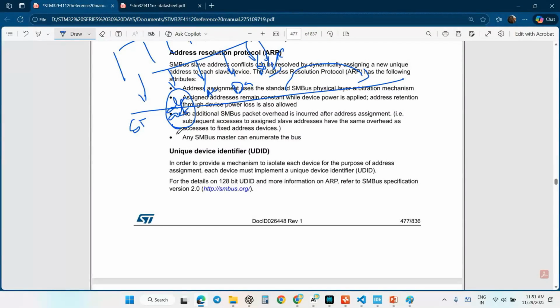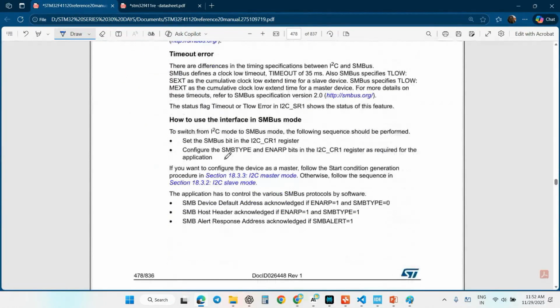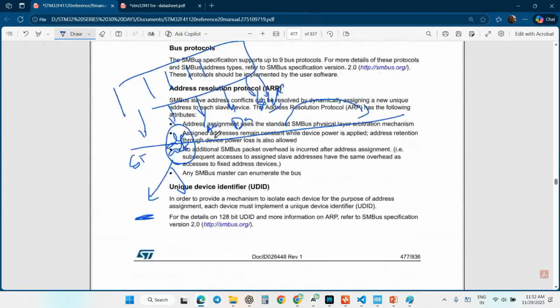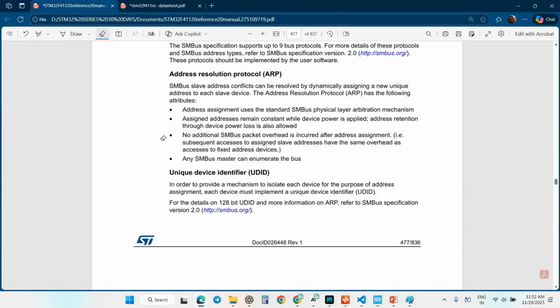If you are setting a data bit, there are multiple procedures. The size has to be mentioned: what data size do we use, whether it is a word or a single character. Based on that, you have to follow every single step they have given. And timing also has to be mentioned, and for that you use a different register. Speed has a different register, and the type of GPIO has a different one. By studying only the reference manual, you will get the complete detail.